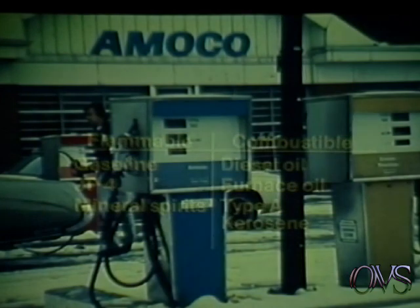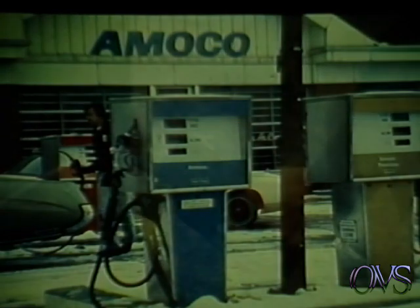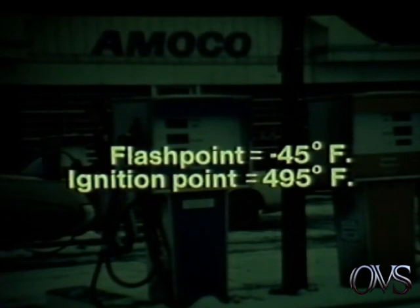In general, Amoco Pipeline pumps two kinds of gasolines for Amoco Oil and for other shippers. These are leaded gasolines and unleaded gasolines. Gasolines are very flammable. The laboratory-tested flash point is 45 degrees Fahrenheit below zero. The auto-ignition point, that is, the point at which gasoline will catch fire without a source of ignition being present, is 495 degrees Fahrenheit. Gasoline produces vapors easily, and the vapors of gasoline are heavier than the air, which means that gasoline vapors will collect in low spots.